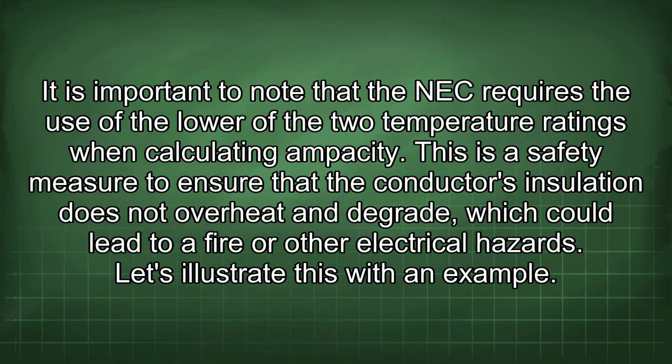It is important to note that the NEC requires the use of the lower of the two temperature ratings when calculating ampacity. This is a safety measure to ensure that the conductor's insulation does not overheat and degrade, which could lead to a fire or other electrical hazards. Let's illustrate this with an example.